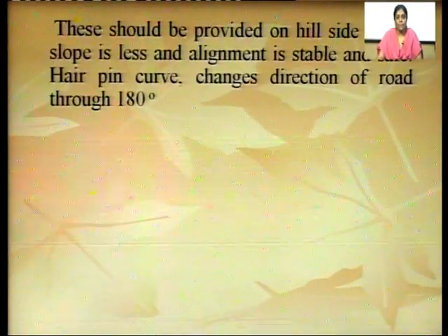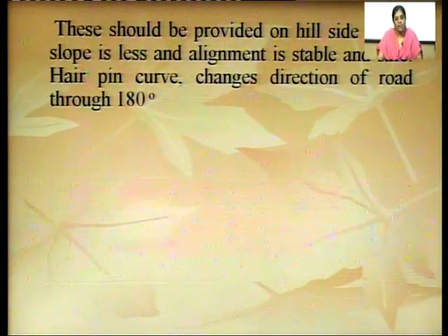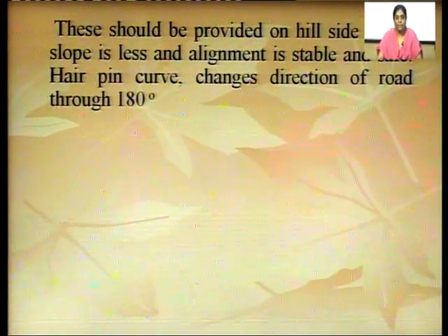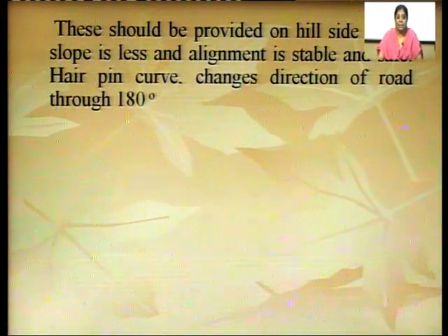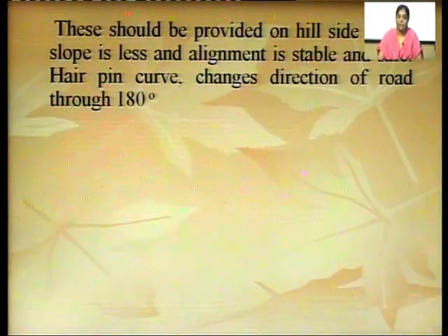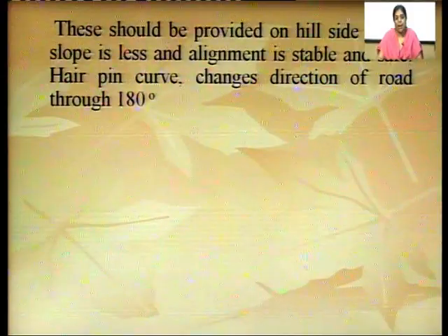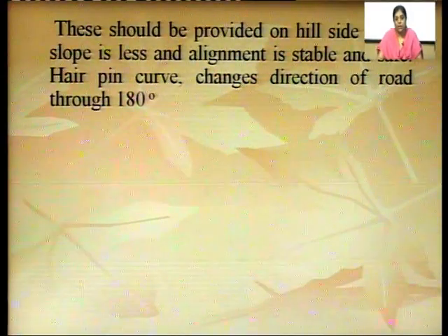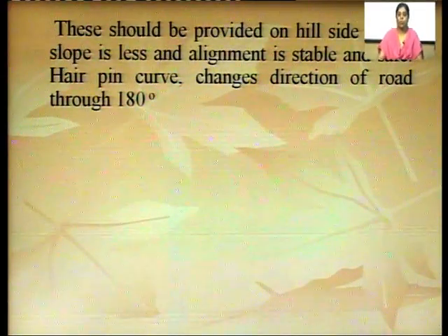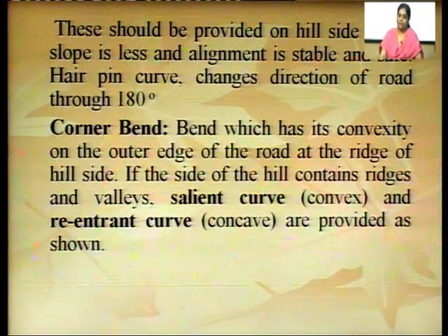So, hairpin bend is generally provided on hillside where slope is less and alignment is stable and safe. So, hairpin bend, as I already told you, changes the direction of the road through 180 degrees.